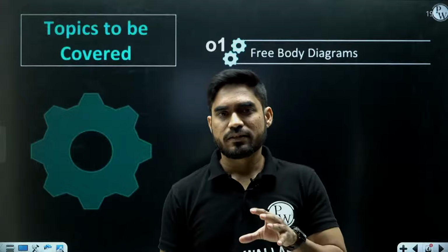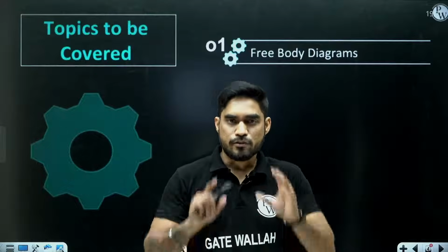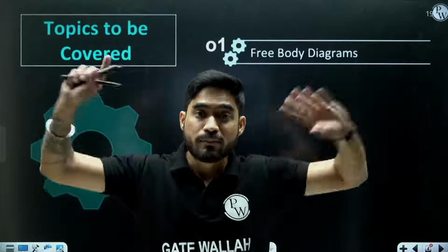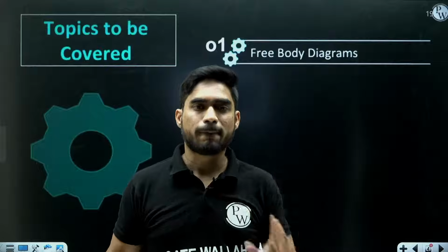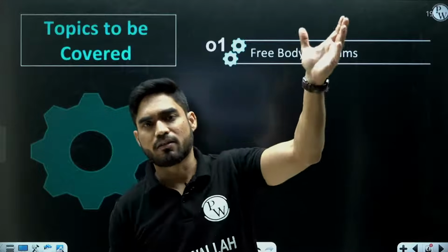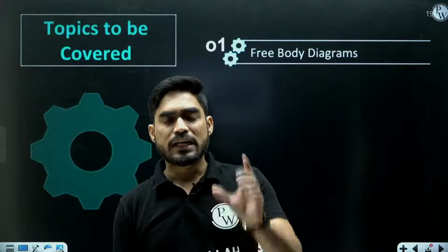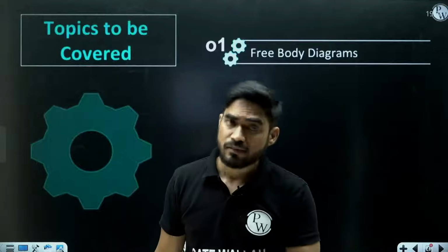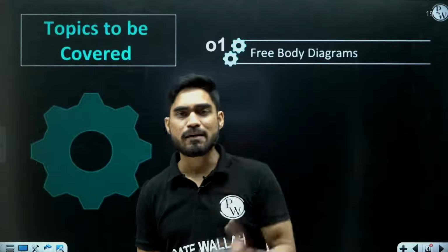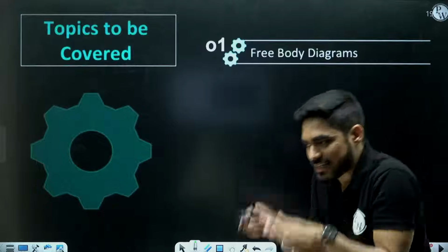Isolating means it is right now connected to all the other members, right? So I have to detach this beam from other members. Okay, and whenever I isolate any member from the beam, I will show the interaction between that member and the beam using forces. For example, the roof is applying a downward force, or the roof is resting on the beam.